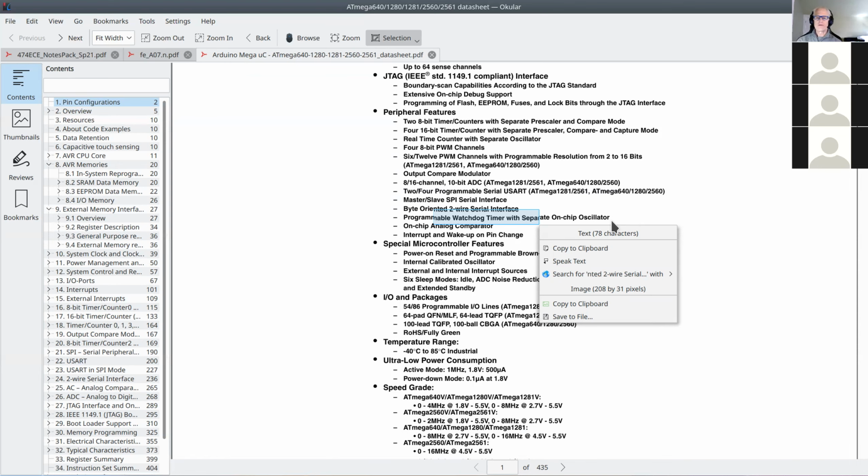The watchdog timer will say, "Hey, I'm here," and the code will not respond. The watchdog timer will do a hard reset. The embedded system will reboot, and hopefully the condition that caused the bug will not recur, at least for a few months or a few weeks, and Thanksgiving will not be ruined. Okay.